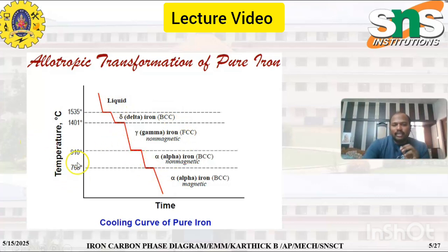From room temperature to 768 degrees Celsius it is BCC alpha iron, and at 768 there is a shift in magnetic property. From 910 to 1400 it is gamma iron, and 1400 to 1500 it is delta iron. Above 1500 it is liquid, because that is the melting point of iron.